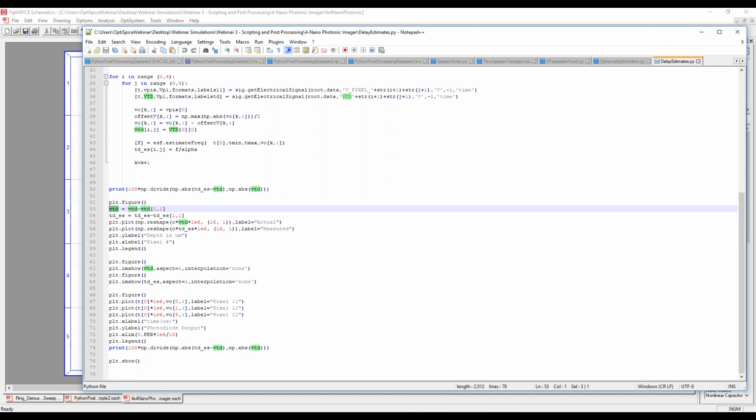In OptiSPICE, we actually don't do the simulation this way. At the first time step, we would generate the results. We would put everything in one large matrix, and then solve the equations simultaneously, and then that gives us the result for the next time step.